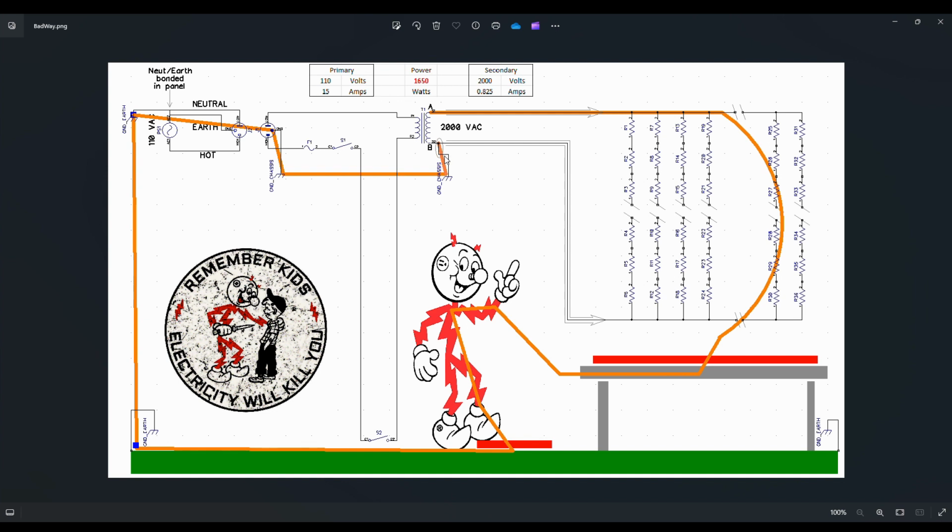And anyway, so it's this connection. Now, if this connection were not there, and you had a failure here, let's say your probe tip wasn't touching your board very well, or it had burned away the area it was touching. Or let's say you've got a connector up here that came loose. Okay? It's okay, because if this connection's not here, B can only pull through the remaining conductor, through whatever conductive path remains to it. It won't be able to pull through the board. So your current will drop to very close to zero.